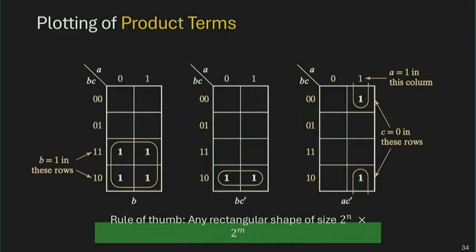And I just want to remind you, in general, these are some of the ways that you can group together min-terms. These 4 ones sitting in a cube can be combined. 2 ones sitting next to each other can be combined. Or you also have to think about the wraparound, the edge and corner and top and bottom adjacency. So that top one and bottom one are adjacent. With this wraparound, they're also neighbors, and they can also be grouped into a single term. And how do I represent that term?